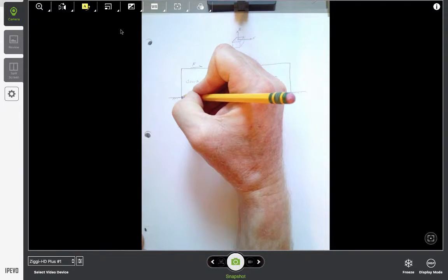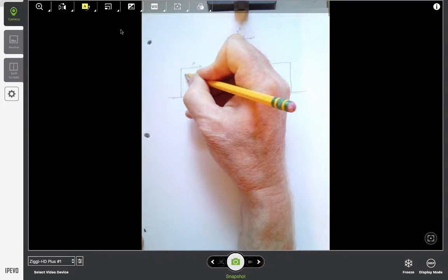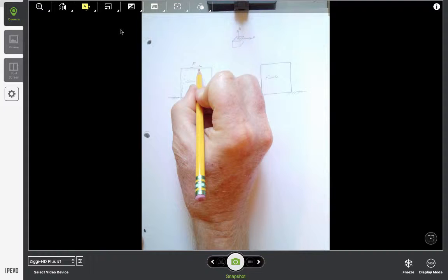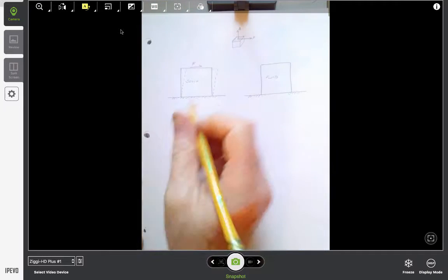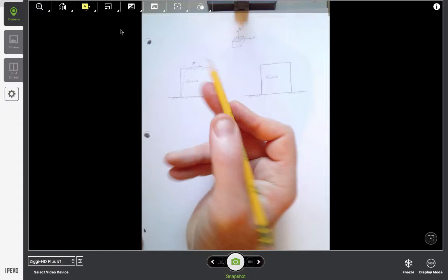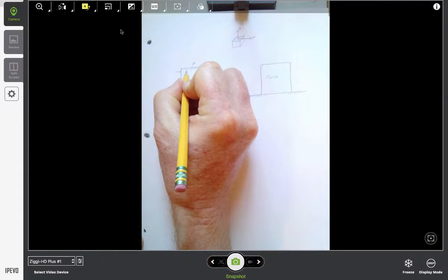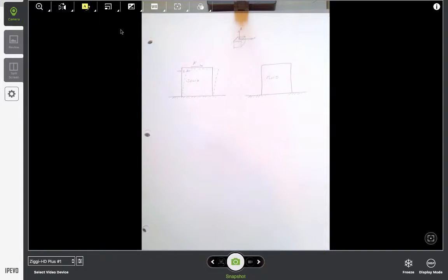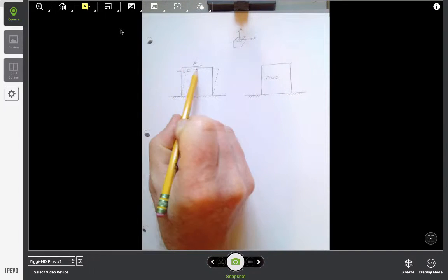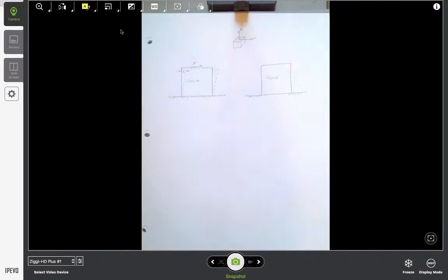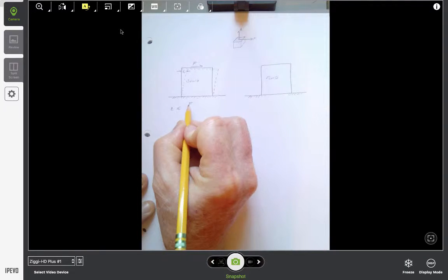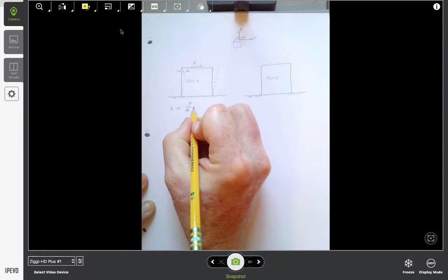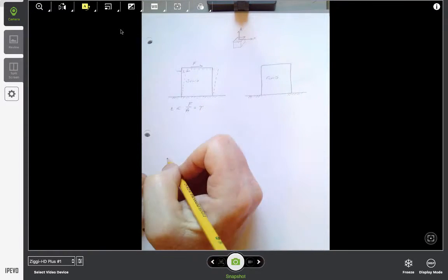And we apply the force, the solid's going to deform a little bit. But as long as that force is less than what it takes to destroy the solid, it will deform only as far as it has to resist the force. And the distance it deforms here will be a distance epsilon. That distance is called the strain, and the force divided by the area is called the stress. So the strain is proportional to the stress, and we'll call that stress tau, the shear stress.